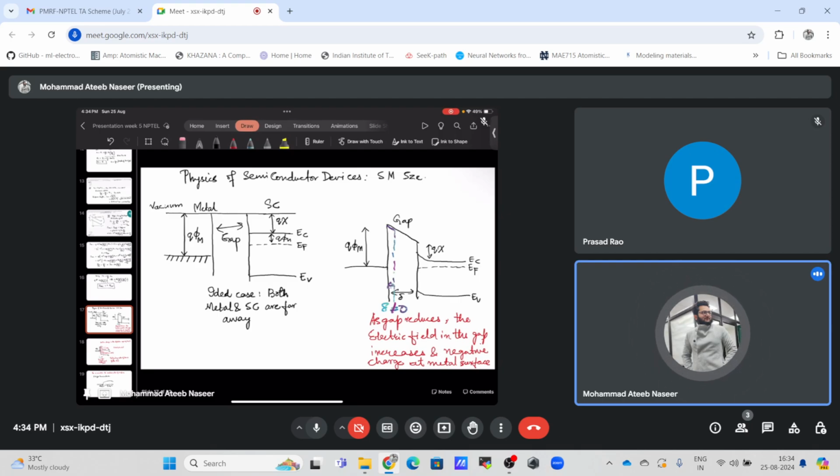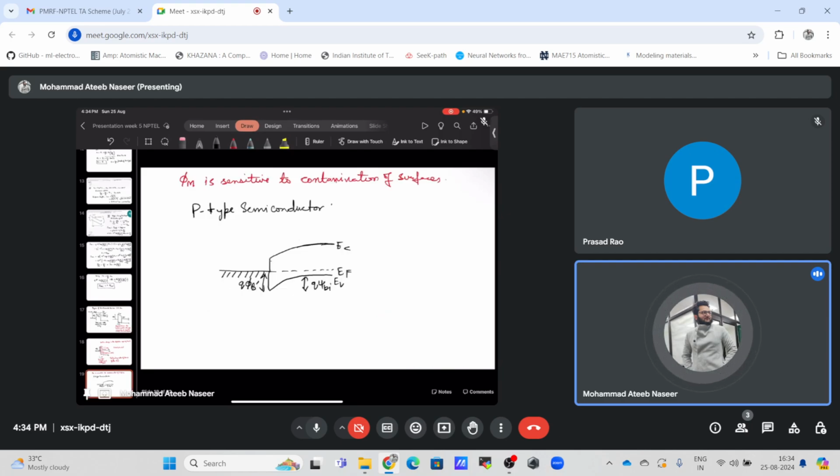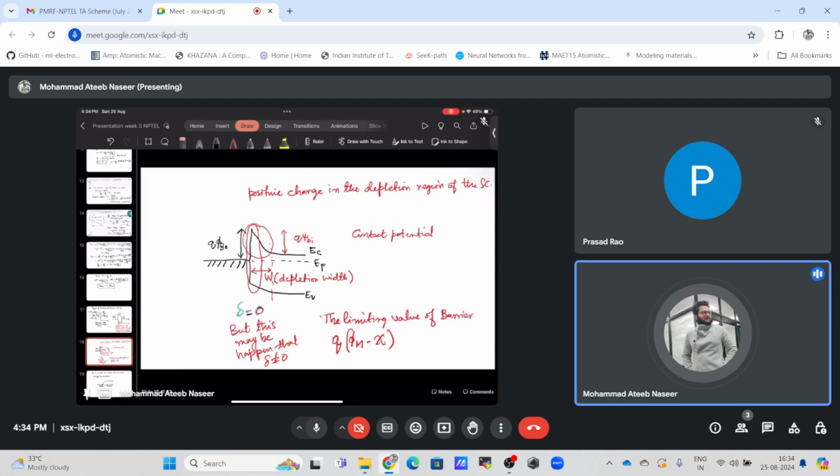And you can see in this case, let me briefly show that there will be five kinds of transport mechanisms for the carriers. But let me just give you one small insight. There are two transport mechanisms that you should know about. One is the thermionic emission, and the other is the tunneling process. Although there will be recombination and diffusion also, just to make it a bit easier,